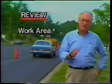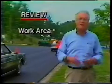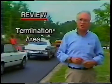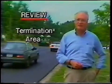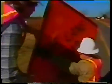The work area is for workers, equipment, and vehicles. The objective is to keep traffic out of this area. And the termination area tells motorists they're out of the construction area and may resume normal driving. This concludes the review of the 5 basic parts of a traffic control zone and their function. In the next session of the series, we'll be reviewing some typical applications that you'll be using in your work.